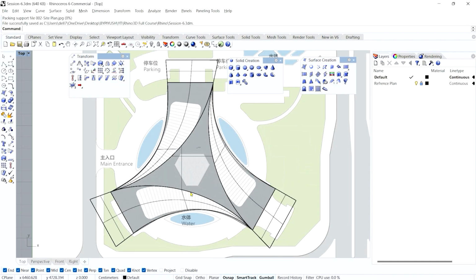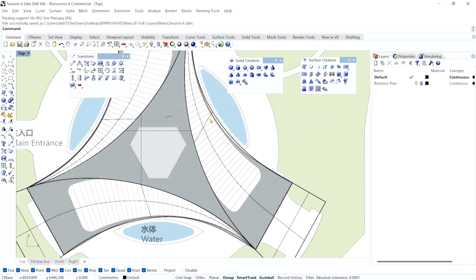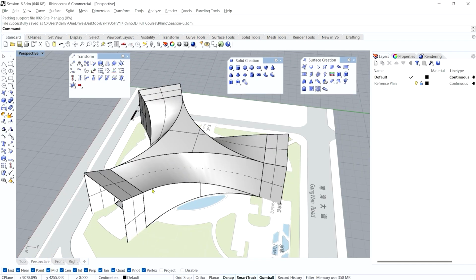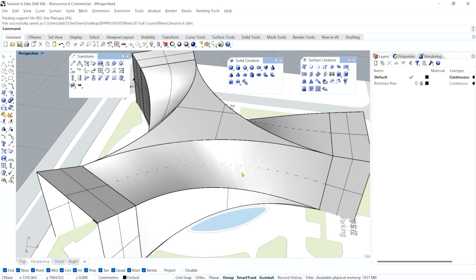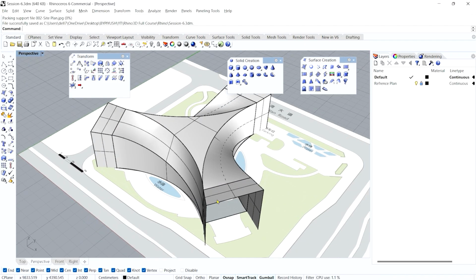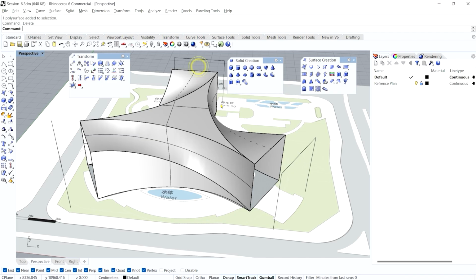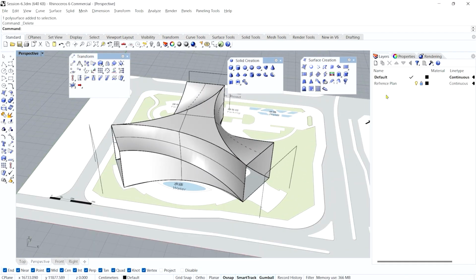Next, we need to create this surface, basically the glass punctures, and this top glass puncture on the curved surface, on this tapered and curved surface. Before that, we don't need these, we can delete them. And if you want, you can create a separate layer for profile curves.